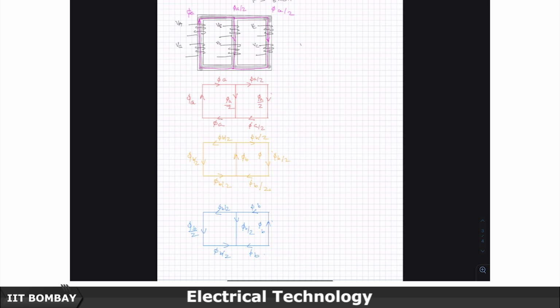be seen. Now, this is a symmetric device, this is a balanced device. So, we assume that RMS values or the peak values of all the fluxes in the three phases are the same, but they are phase displaced by 120 degrees, and they all are basically phasors that we are representing, which means that they are actually, these flux waves are also sinusoids.